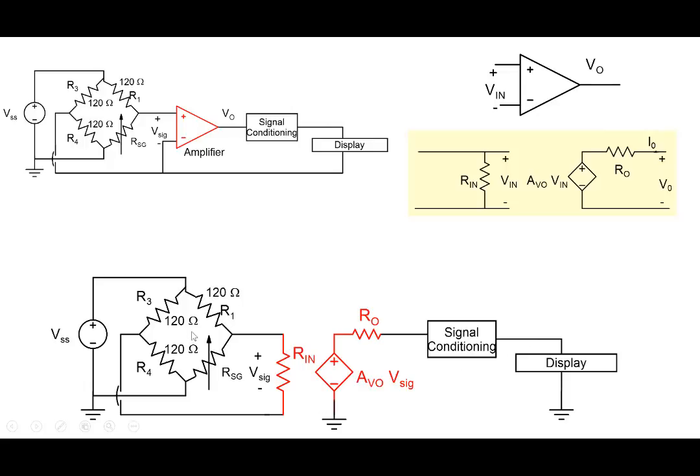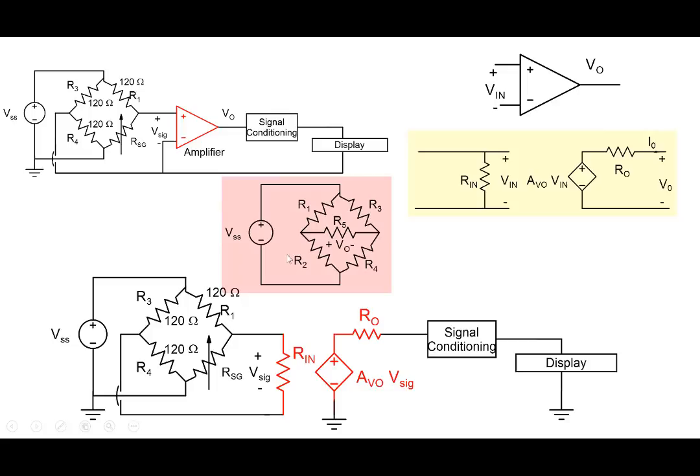And we can redraw this into this particular form here, right, as a more general form. So we have 4 resistors, and in between also we have a resistor here. So this is the Wheatstone bridge circuit that you're well familiar with, and we analyzed it, and as all of you know, when it is balanced, then the voltage across V0 is 0.